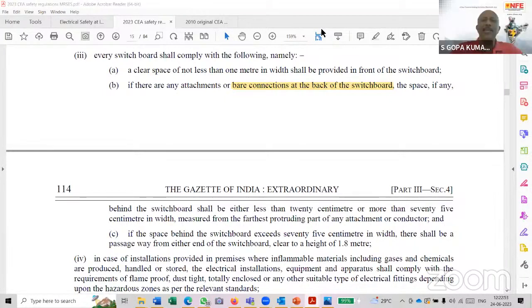Sir, one thing, Gopal Kumar, I would like to add. In our NEC Part 1, Section 22, that speaks about electrical safety, we have given the arc flash distances, clearances, restricted area, prohibited area. Like that, we have clarified what the distances are, and that is as per the arc flash hazard assessment. So whatever they have mentioned here, 1 meter or 20 centimeters, that doesn't correlate with the requirements we have given in the NEC Part 1, Section 22. So this regulation should be reviewed from that point also.